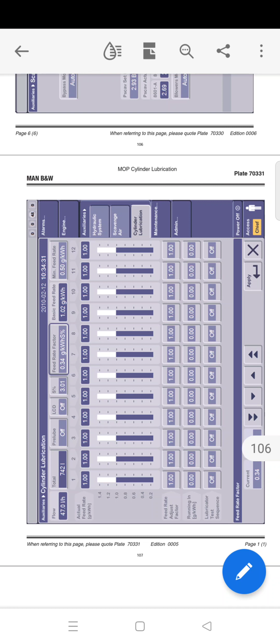Running in, gram per kilowatt hour: when a single cylinder is being run in, the feed rate is adjusted on this display. Running in of a single cylinder is described in section 70701 in this book. Now lubricator test sequence: pressing the lubricator test sequence starts a continuous activation of the lubricator at normal injection rate, different from pre-lube, and injection of oil is done 20 times at the fastest possible speed. This feature is used after repairs. It is on the lubricator, enabling the engineer to manually check the lubricator for leaks and injection.